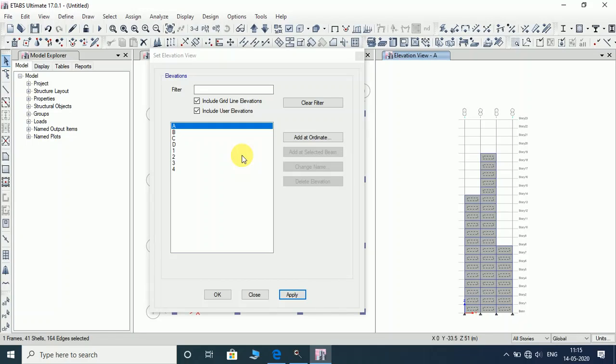Then by finding the suitable portion in which this value of 3.83 falls, there are two subcategories into it where W by L ratio is taken. So here W by L ratio is 1. So again select a factor where the ratio is between 1 to 6 or 1 to 3 by 2. So select that portion. In that portion, for A side of the plan, we have 0.8.